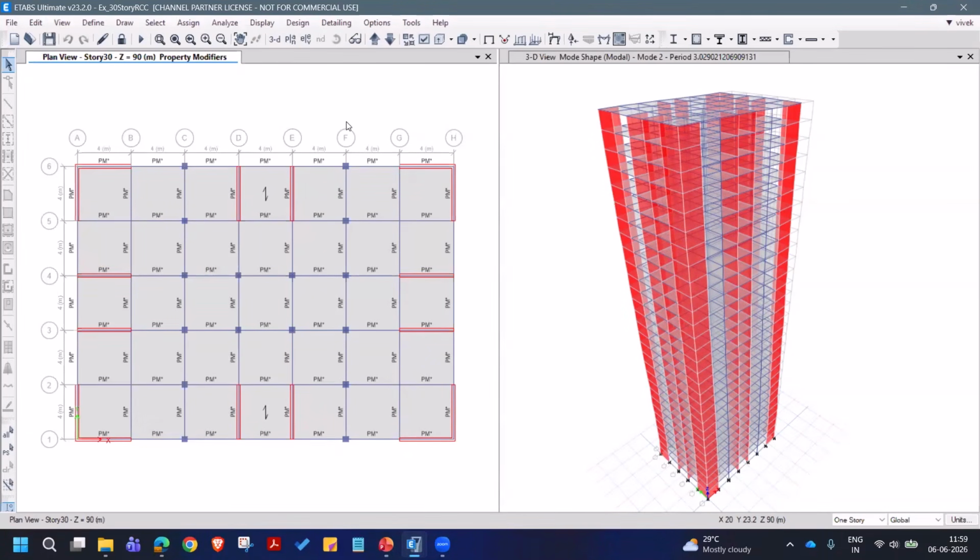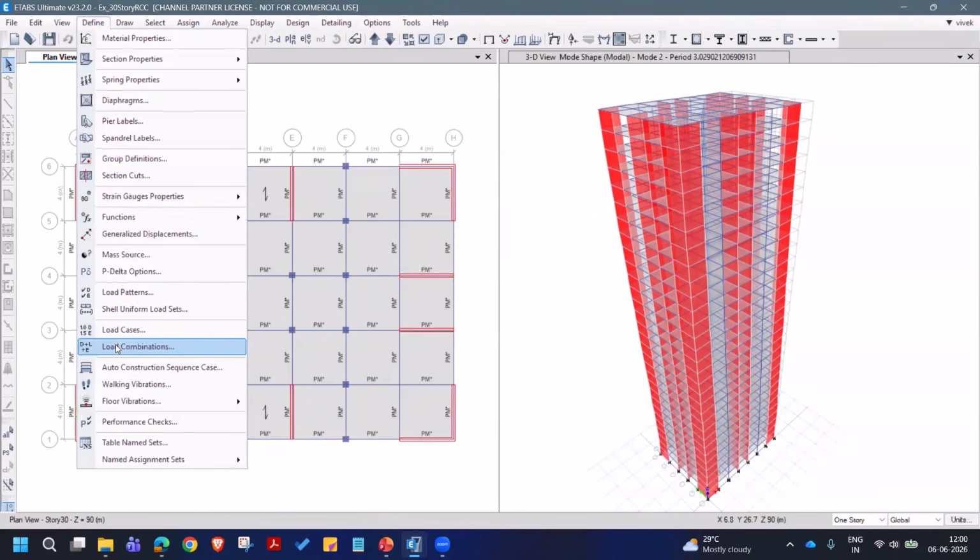From here, the design basis would be IS 456 and other criteria through the ductile and seismic provisions of IS 1893 and 13920 as applicable, and you can proceed with the design. If you have any special combinations that you are introducing, then you'll have to define load combinations other than the default ones and use them in the design.